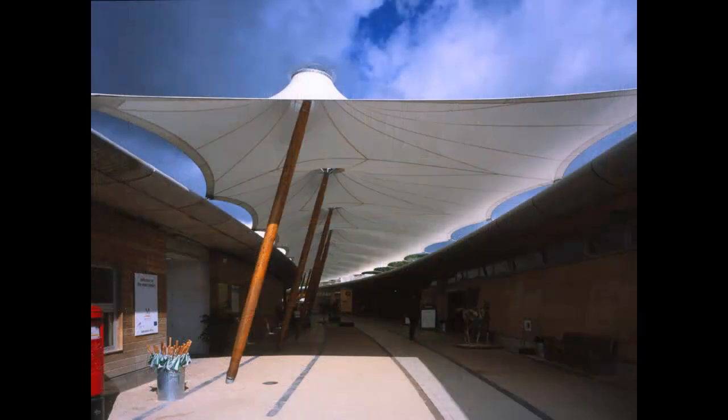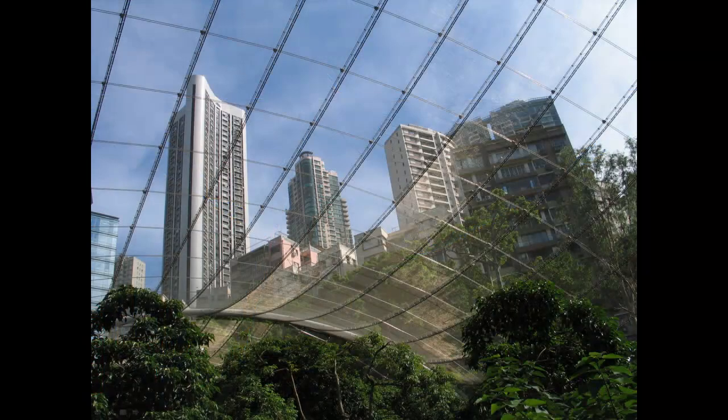In other situations such as roofs and long span structures, there is more flexibility, and you've got the opportunity to make something light, elegant and efficient, such as this fabric roof from the Eden Project down in Cornwall. Now, these lightweight structures resist loads not by inherent stiffness like the steel beams do, but by their form, their shape, their pre-stress and quite often large deflections.